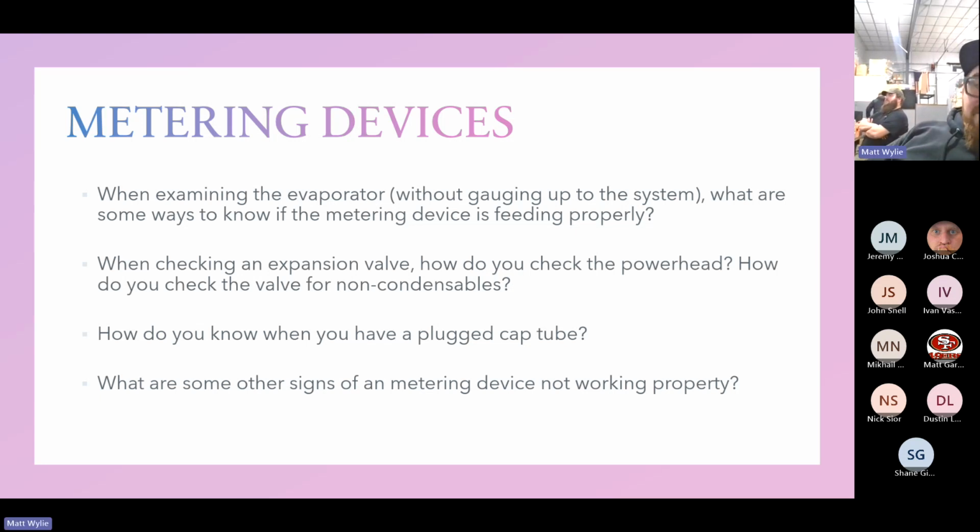When checking an expansion valve, how do you check? How do you check the power head? How do you check the valve for non-condensables?